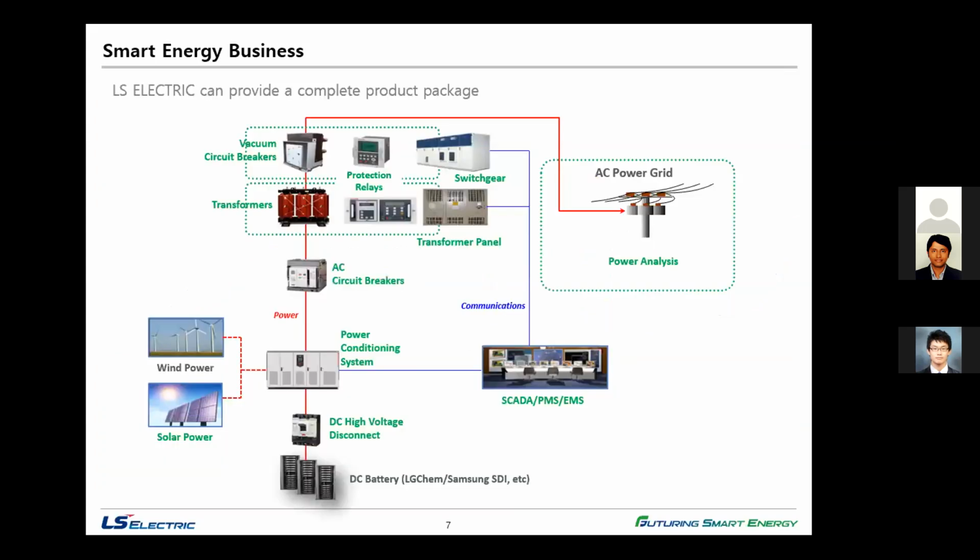So now I want to talk about the energy storage system. The energy storage system concept is pretty much the same as the PV inverters. The only difference is that instead of a PV inverter, we have a PCS, power conditioning system. Basically ESS, energy storage system, means any system storing heat, location or mobility energy. But in our business, we particularly define it as a battery-based ESS, to charge and discharge in order to keep the system as convenient as possible.